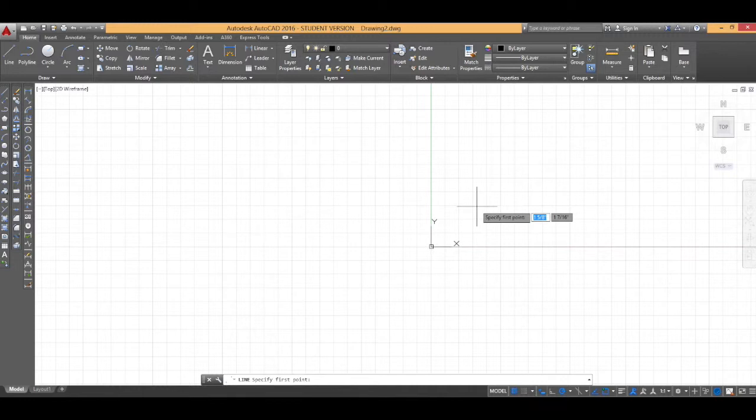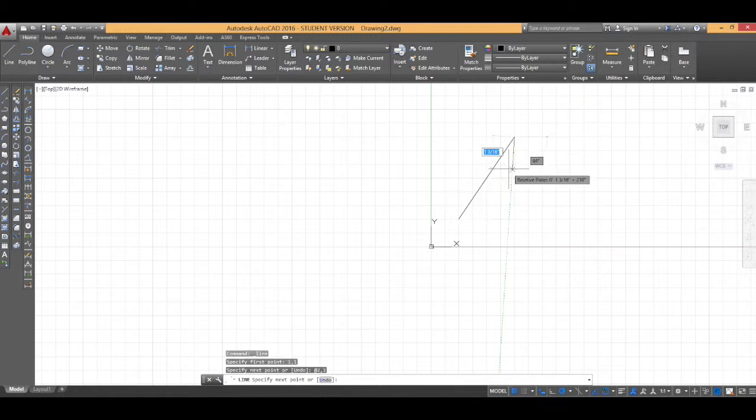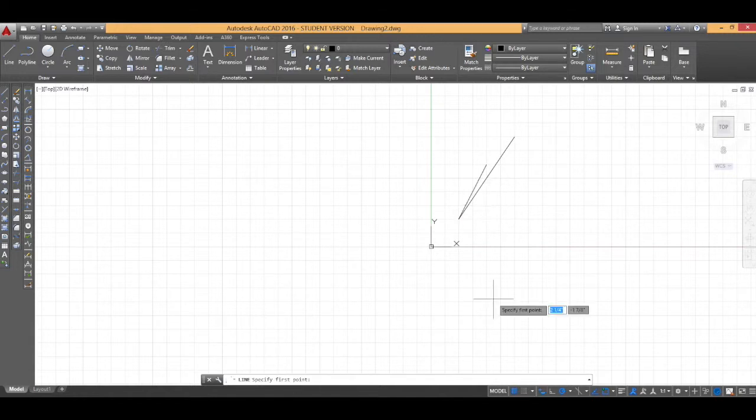So like from our first experience with the line command in the polar coordinate system, we can still type 1, 1 for our starting position. But now, if we type 2, 3, it goes 2 and 3 up away from this point, as opposed to, with the polar coordinate system, to that exact point on this system. We're going to primarily use dynamic input because of its ease in typing our distances when creating walls and features.